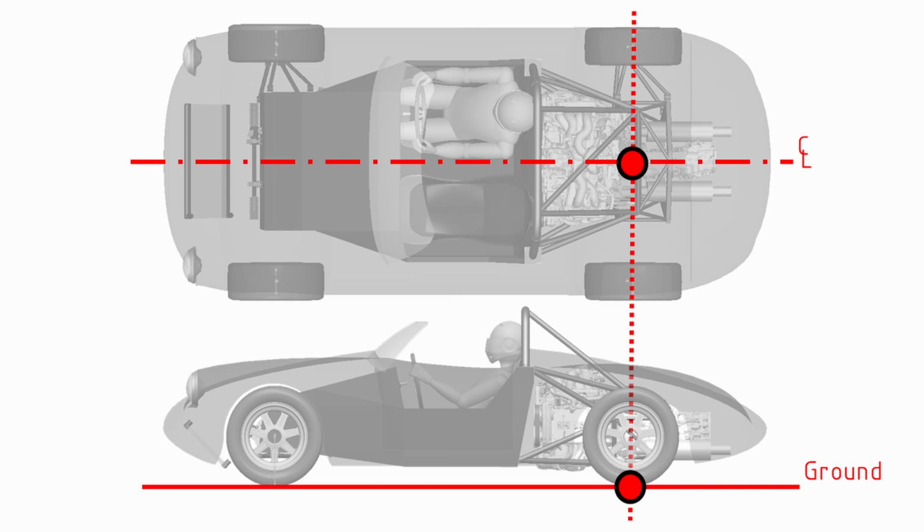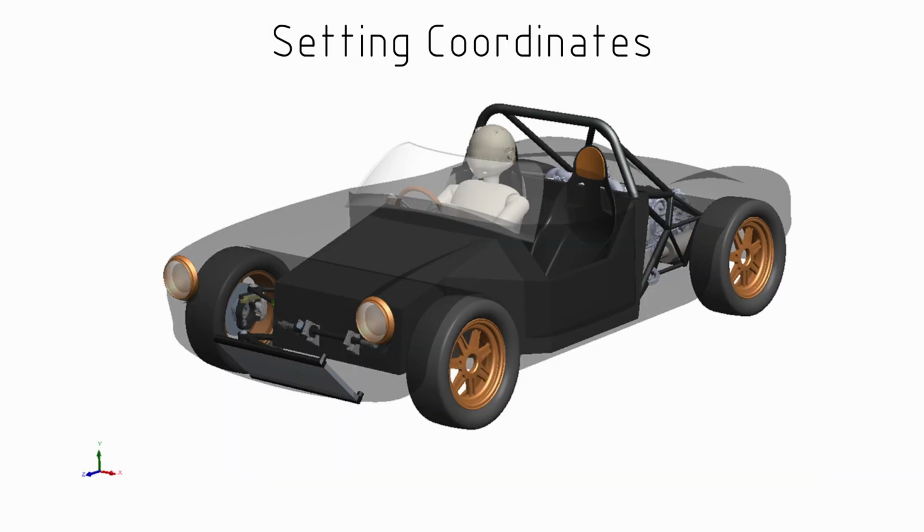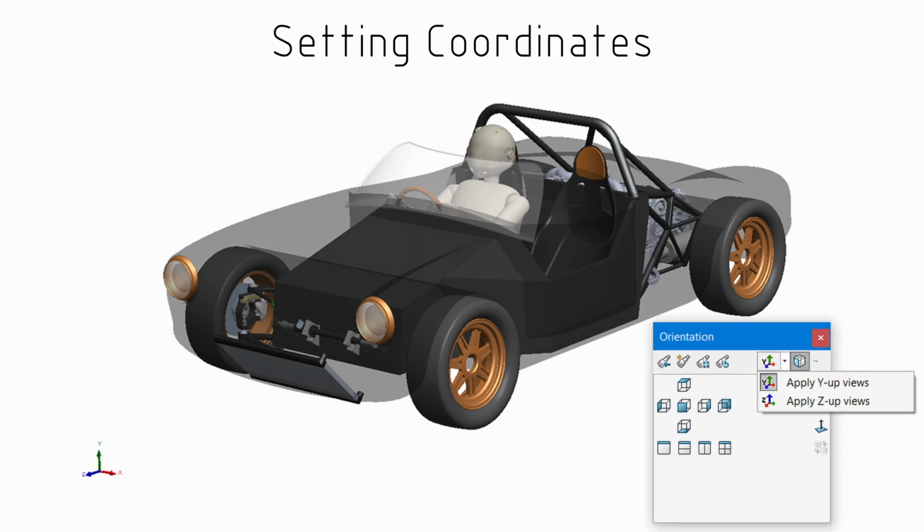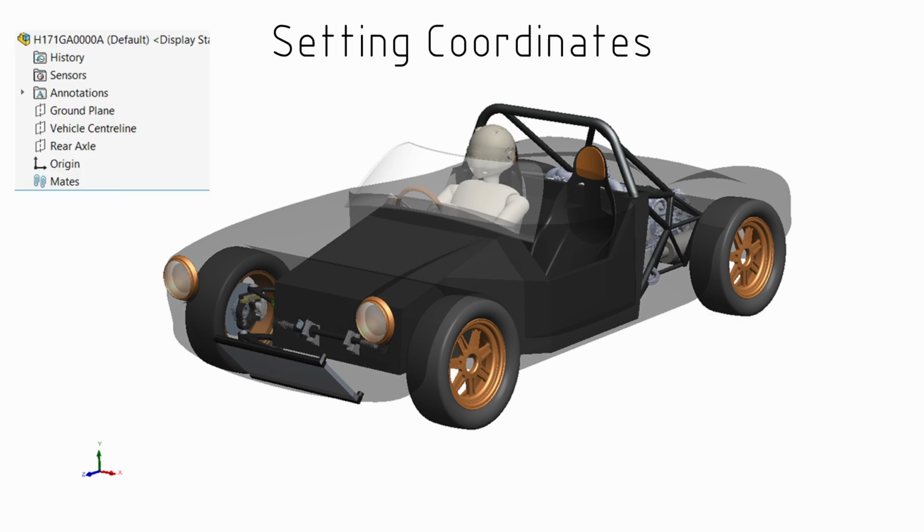One thing you'll note if we go into a SolidWorks model is that by default, SolidWorks will have Y as the vertical coordinate. Now we can change that by going into the view properties and turning that to Z on the up axis, and it relocates all of the different views. Then we should go through and rename those planes, especially of the main CAD model assembly.